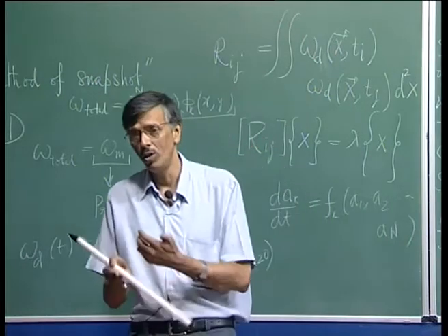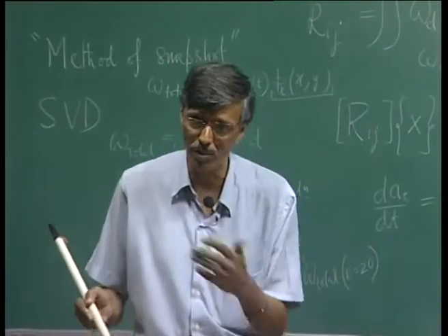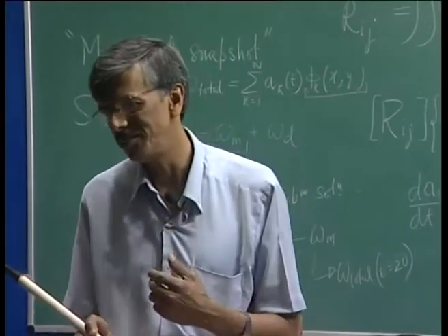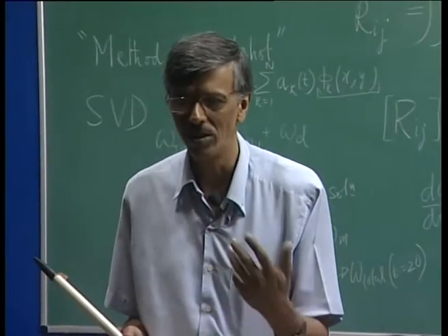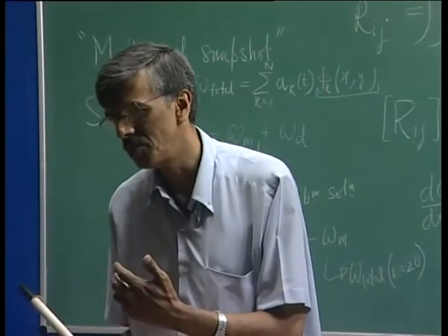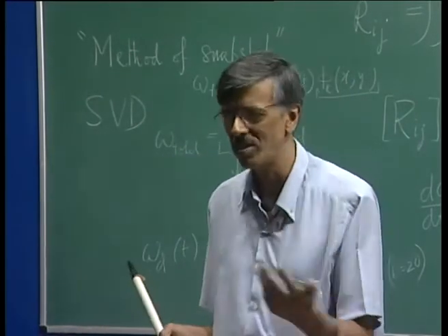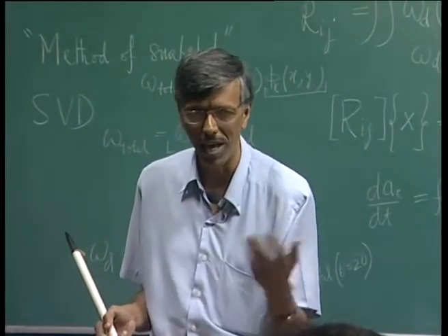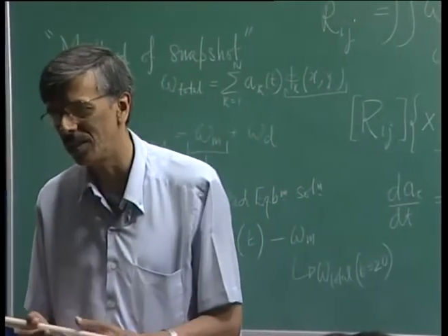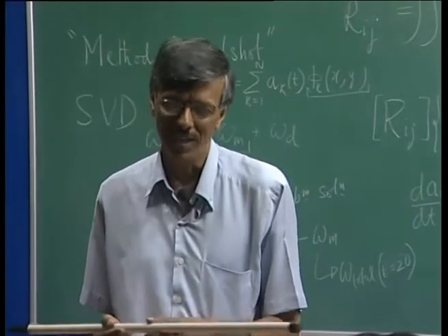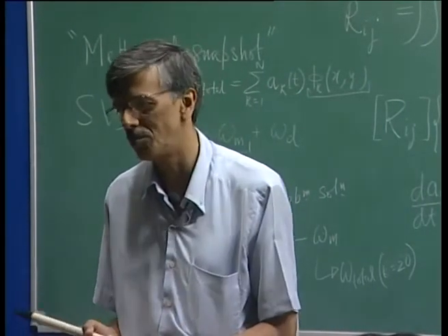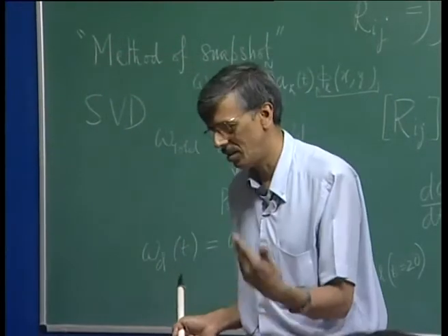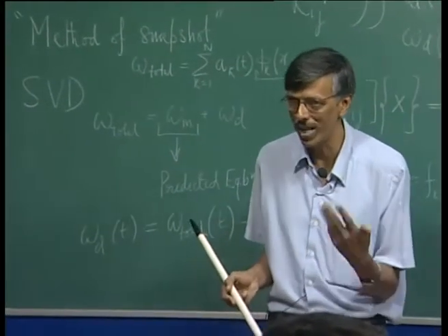And there is also a possibility which came about much later, that you make the shock absolutely weak, and those are called the supercritical wings. They came about in the 60s and 70s. In fact, these days most of the aircraft that you fly, commercial long distance airliners, all have these supercritical sections and wings. These are called natural laminar flow wings.